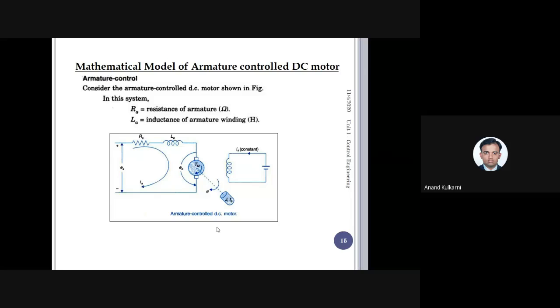Naturally, you might have seen in the market that most induction motors have either 1500 RPM, 750 RPM, 3000 RPM, and so on. They are used when you require a constant speed. Induction motors were used in olden days when there was a constant speed requirement. But when you want a variable speed motor, the problem with the AC motor is with the torque generated by the motor. You know the power equation: power is equal to 2 pi N T upon 60.